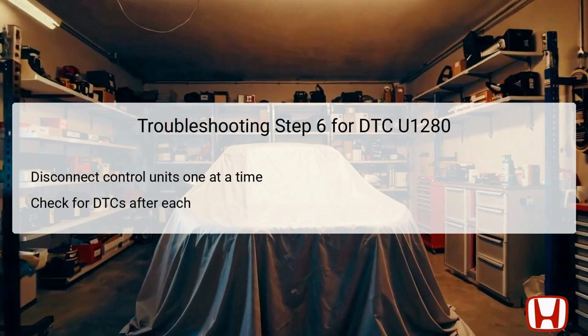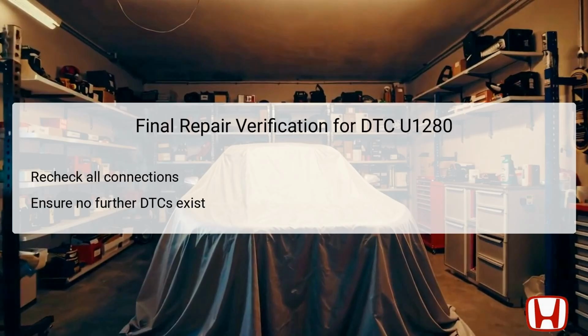By isolating each unit and assessing whether the U1280 code reappears, you can effectively narrow down the problematic area within the vehicle's communication network. This systematic process is essential for accurately diagnosing the fault and ensuring that it is addressed appropriately.